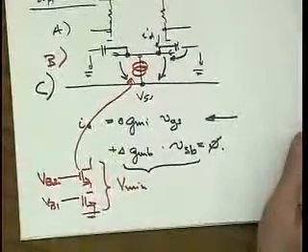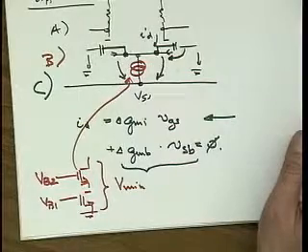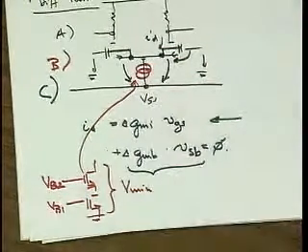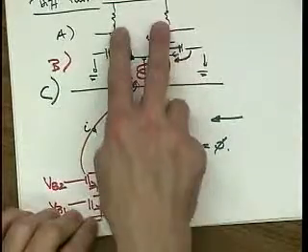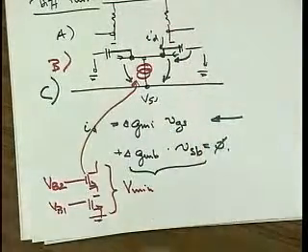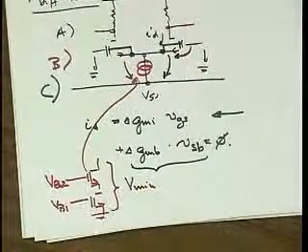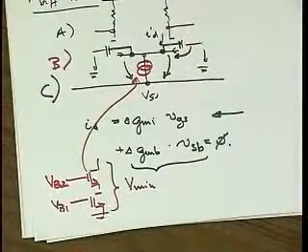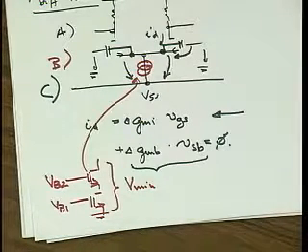Yes. How important is the matching for the resistors there? Same thing, right? If they mismatch by 1%, it doesn't matter whether the transistors or the resistor mismatch by 1%. The current splits according to the total impedance in here. How do you compare the mismatch of the resistor and the transistor? Is it easier to match or harder to match for resistor?